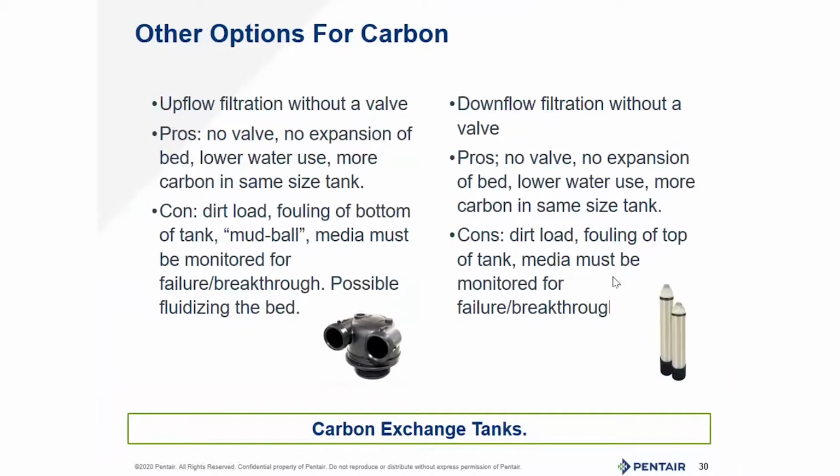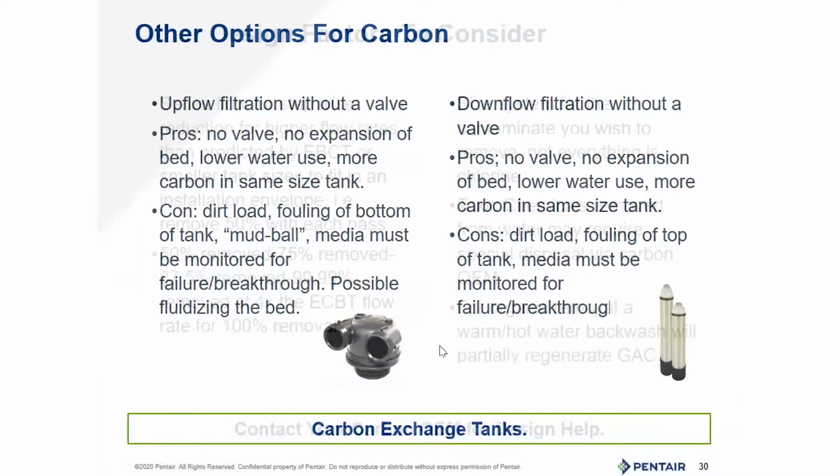And sometimes that's done in series flow where you're sizing it for a 50% reduction through each tank rather than a single pass system. That's how these are leveraged in a lot of ways. So let's say you've got a small, low-level area to get into and you can't get backwashing valves in or a large tank in. That's where series exchange tanks come into play. So understand that's out there as well.